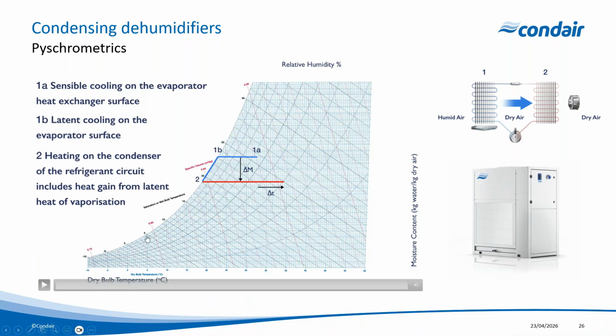Now, if the apparatus dew point, so the mean temperature across the coil, is, let's say, 6 degrees C, then we know that is the minimum absolute moisture content that we're going to get to. Well, if you take that up and heat that air up to 21 degrees C, we're going to be around 40–45%.